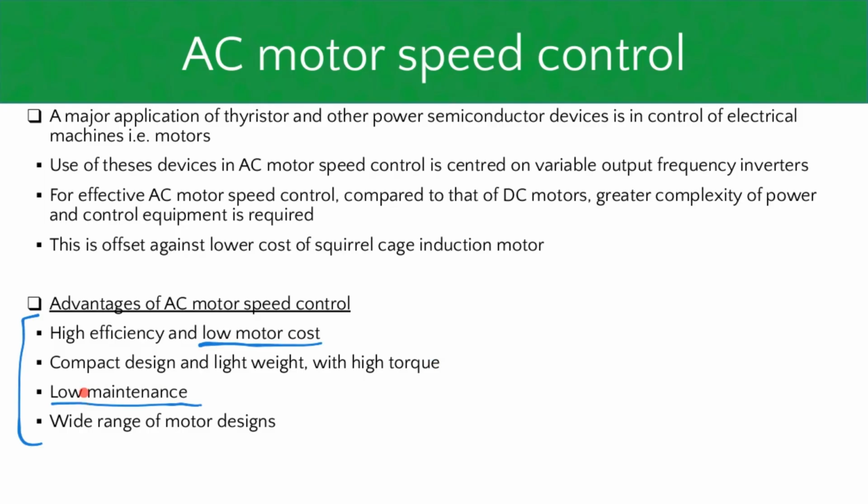Also, DC machines, just think about it for a second. If you have carbon brushes getting worn out, where does that carbon go to? The carbon dust just doesn't disappear. It goes somewhere in your machine, and it can cause issues. It can be a fire hazard. It can cause short circuiting on your terminals if it somehow manages to get into your terminal box. So there's a danger.